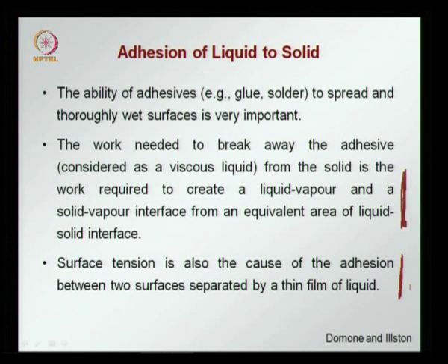We also know from this explanation that when we have to use an adhesive such as a cyanoacrylate, one of these quick glues, we have to produce a thin surface of adhesive. The adhesive layer should not be very thick. The thinner the layer of adhesive, better is the bond, because then the surface forces are larger.